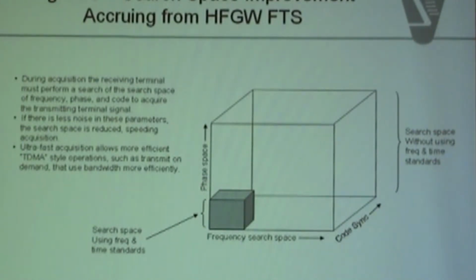And so, for instance, where a handset, when you first power it on, might take 30 seconds to do an acquisition search before it finally achieves the signal, it could be done in milliseconds. What this really means is that the dead time when no one's talking to you and you're not talking to anyone else could conceivably just drop the link. And this link could go up and down whenever data is being transmitted. But the rest of the time, during the dead air period, you could simply drop the link and reacquire, because reacquisition is so quick that the speaker wouldn't notice that the link is dead, essentially.